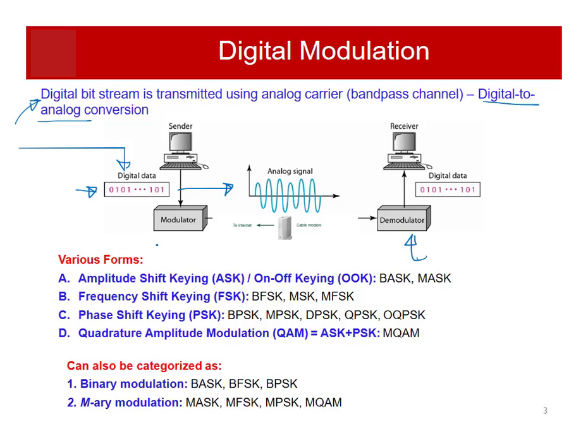So let's talk about the various forms or classifications of digital modulation. But at first, I want to draw the similarity between digital modulation and analog modulation. For analog modulation, we had AM, FM, and PM. About the nomenclature or naming of these modulation techniques, they had something in common: we had a carrier signal c(t) and a message signal m(t). The carrier signal was varied in some way depending on the message. So the carrier signal is transmitted, but some property of the carrier is modified according to the message. This was the whole idea about modulation.